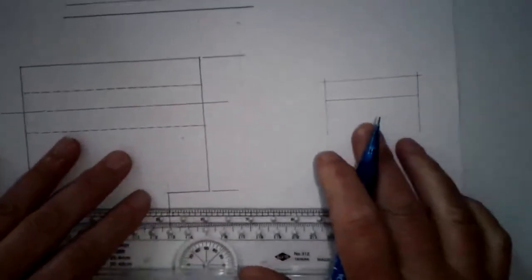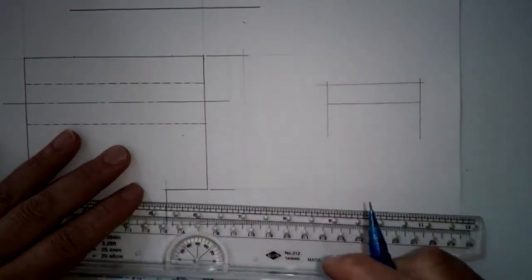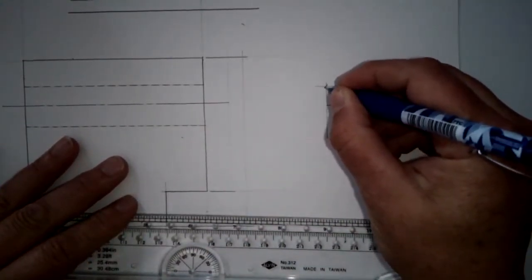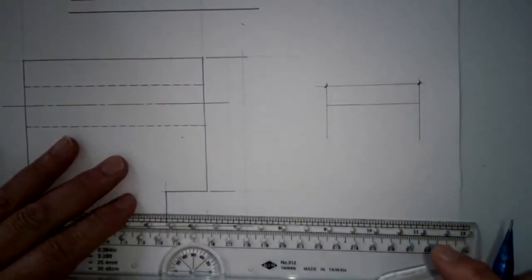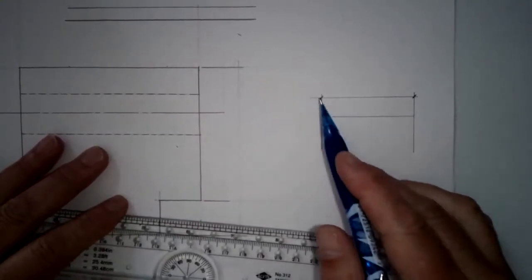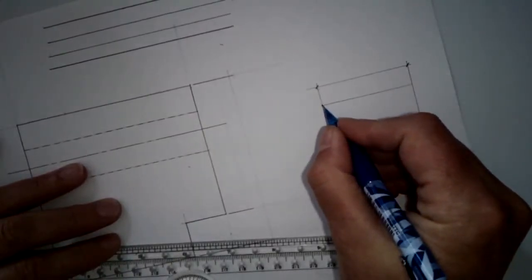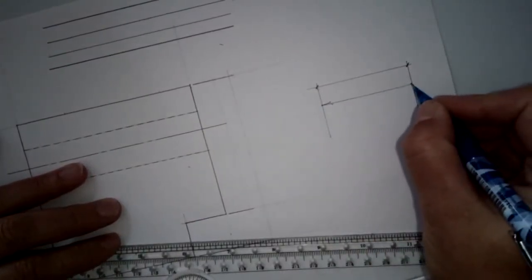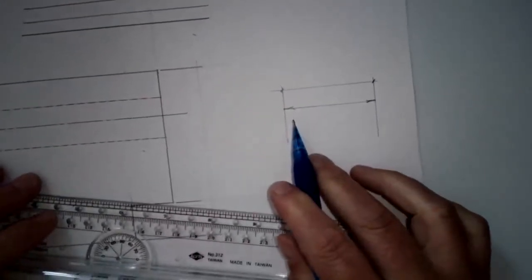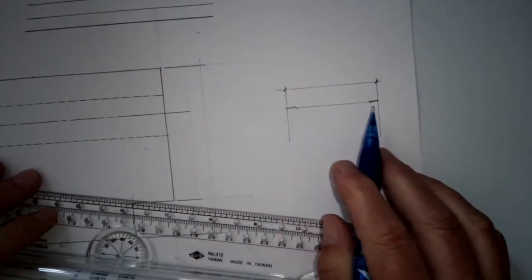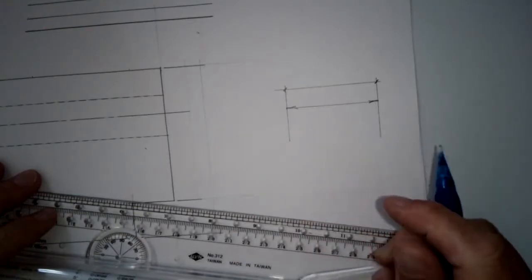So an architectural dimension, both the dimension line and the extension lines extend past each other, and then you define where your dimensions are going from and to with what's called an architectural tick mark. That's what we have here. A mechanical dimension, you define where you're going from and to with arrows, and you can see how I'm drawing these arrows as narrowly as possible on the ends of the lines, because as soon as you see that, we can see that this dimension is going from extension line to extension line.